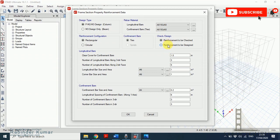So always go with reinforcement to be designed. That's why we are using the software. If everything is given by a user, then there is no use of this software. So reinforcement to be designed. Click OK.